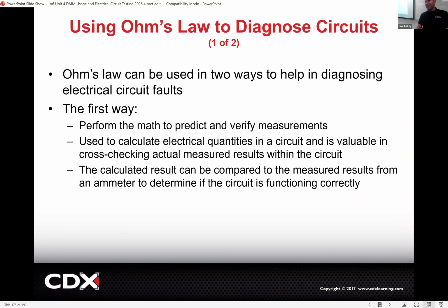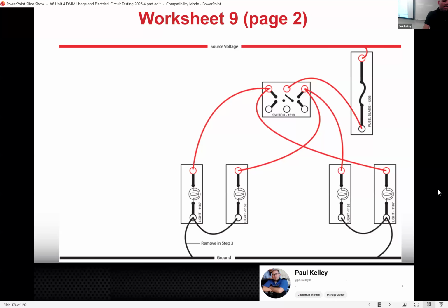And all this really is, this is a switch that's just a little bit like a multifunction switch or a hazard switch or something. This, if you look at it, is really just a number of different switches. So like, if you follow this wire, it comes into this point. Is it connected to anything? No. So you'd have 12 volts coming in here, you'd have 0 volts on everything else.